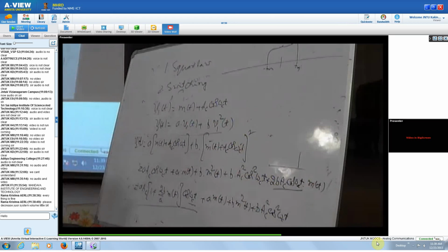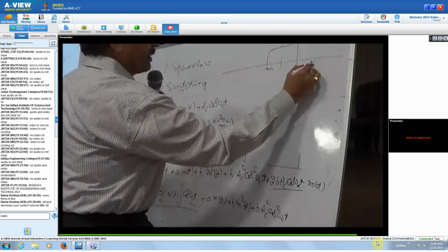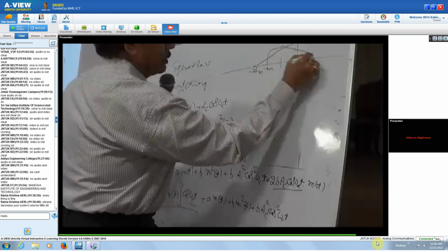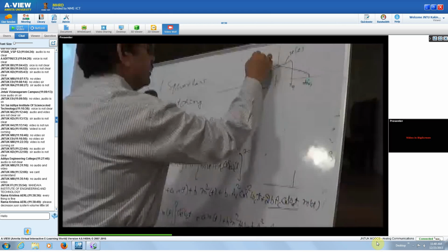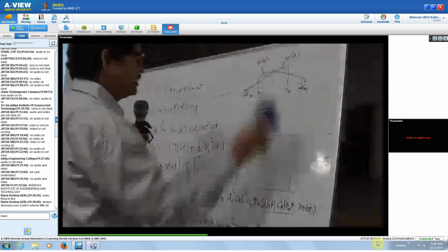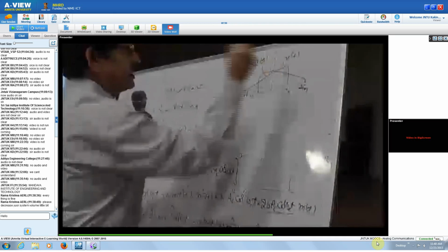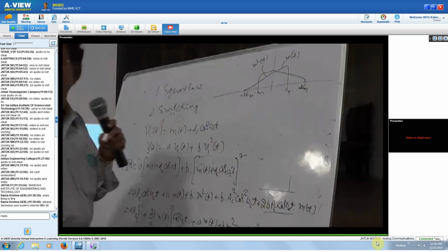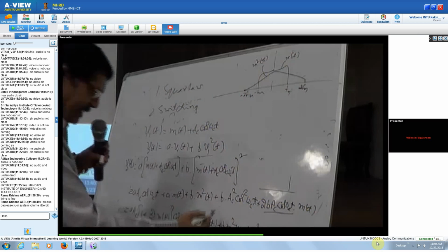When it comes to the square, you get the second harmonic, so from fm it extends to 2fm and minus 2fm. This is M(f), and this spectrum is for m squared(t), while this is for m(t). So m(t) lies between minus fm and plus fm, whereas m squared(t) spans minus 2fm to 2fm. These two have been taken care of.